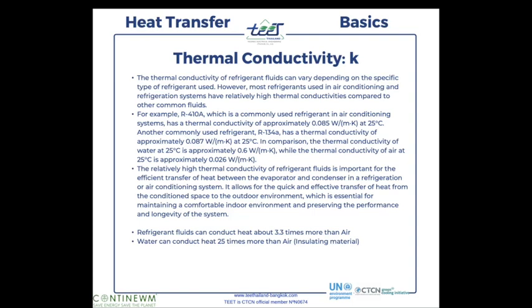And if you compare with the thermal conductivity of air, it's not very high, it's much lower compared to copper, for example, if you remember the numbers that were very high, but it's still much higher than air, because the thermal conductivity of air is 0.026 compared to 0.085 for the refrigerant fluid, okay? So we convey the heat still more than 3 times more with a refrigerant fluid than with air. That's why we use it, okay?